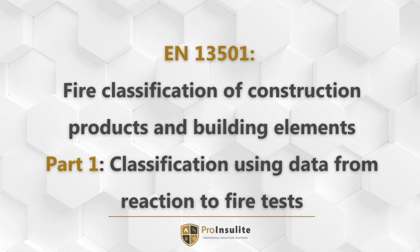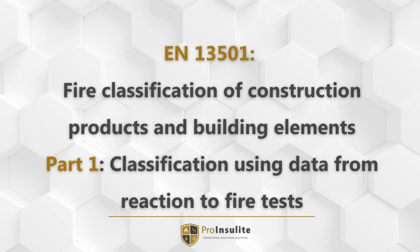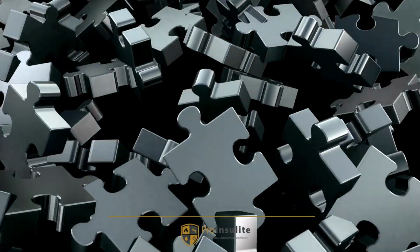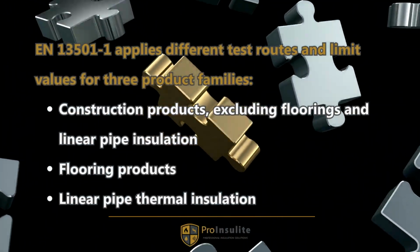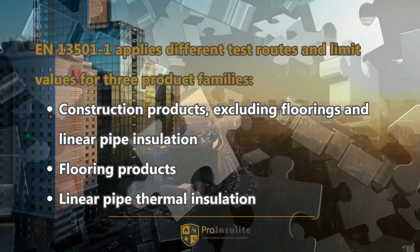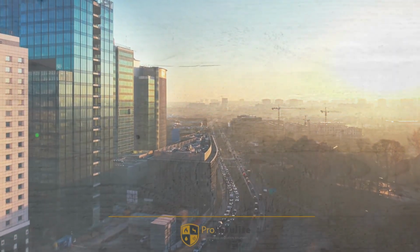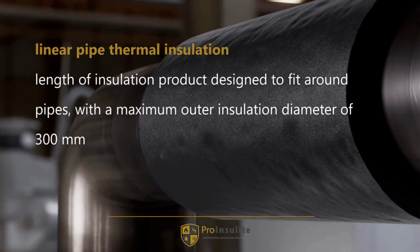EN 13501 Part 1 defines how construction products are classified by reaction to fire performance. This classification is not based on a single test. It is a sequenced system, and the pathway varies by product type. 3 product groups are defined. Construction products excluding floorings and linear pipe insulation. Flooring products. And linear pipe thermal insulation.